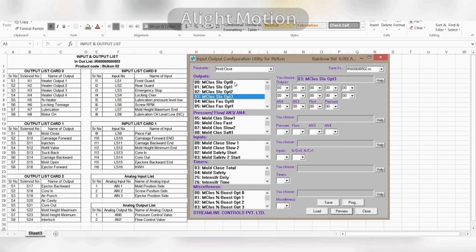You can see the output number 9 of mold close is defined in our wiring list. So we will define output number 9 in all options. You can also see that there are 2 proportional outputs in our list, such as pressure and flow. So we can see pressure, flow, AN3 and AN4 in the output box. If you have 4 analog outputs, then you have to enable all 4 by 0 1. We have 2 analog outputs, so we will enable pressure and flow by 0 1.